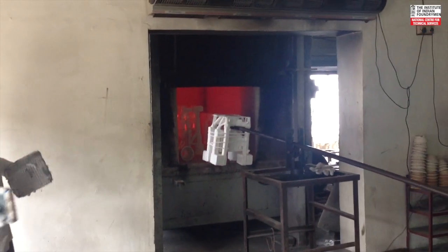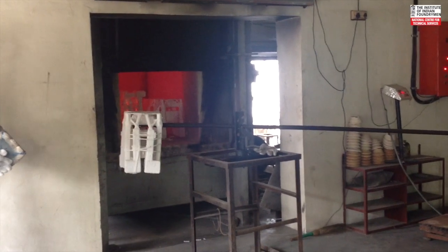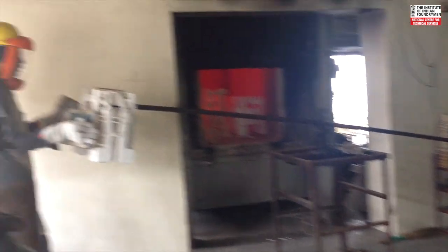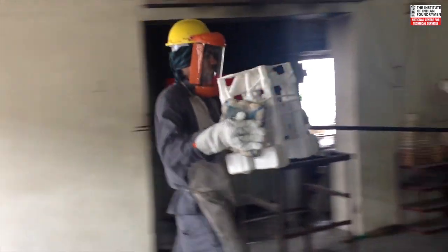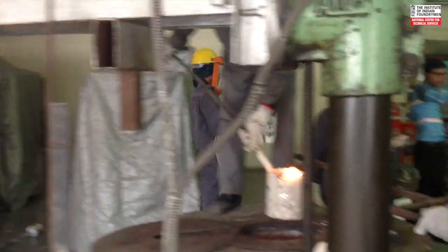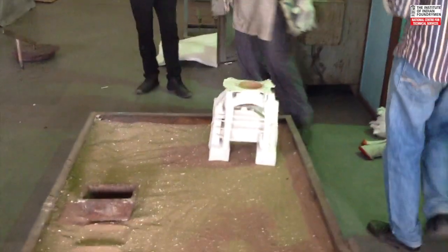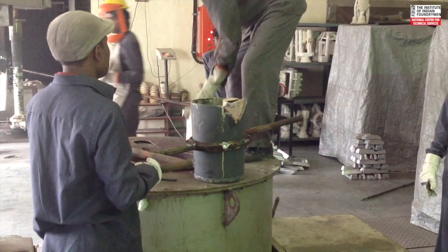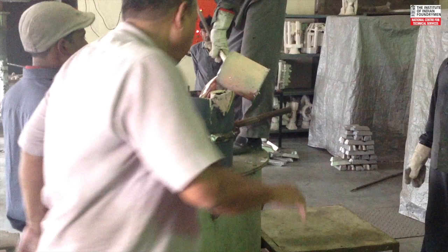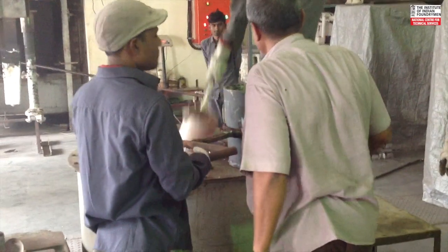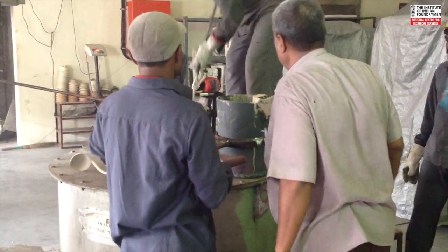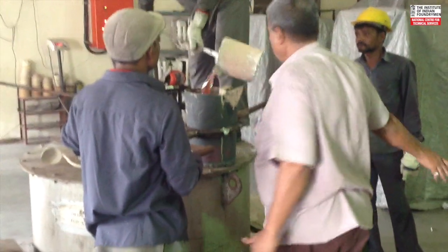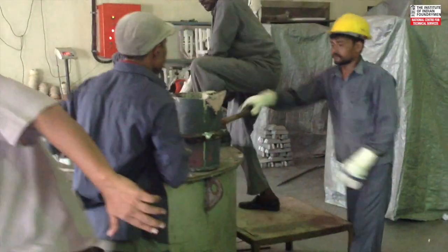In case of investment casting, a wax mold or wax tree is prepared initially. It is further coated with multiple layers of refractory coatings. After proper drying of these coatings, this assembly is first heated to drain off excess wax, and then it is heated in a furnace so as to get a ceramic shell. In such a hot shell, metal is poured, thereby delivering very, very fine surface finish and intricate shapes.